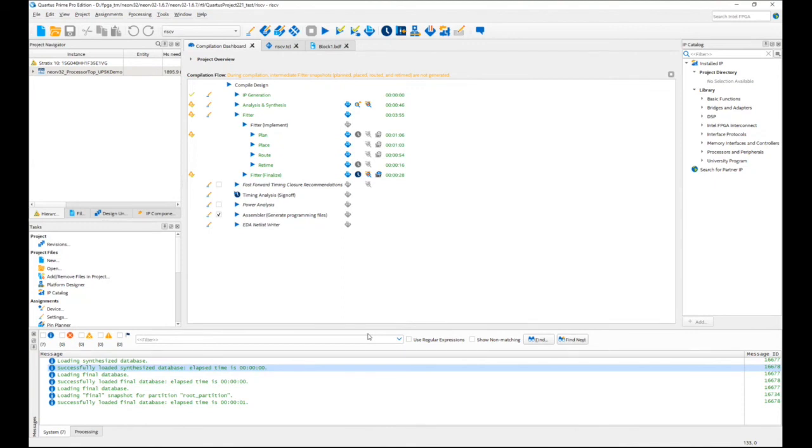It has to start at some spot. So there is something called a seed, and the term seed is kind of overloaded, because there is a seed value that you can change in a compiler setting, but there's also a seed number internal to the tools. The tools use this seed number to decide, I'm going to start placing and routing the design at this location in the FPGA.